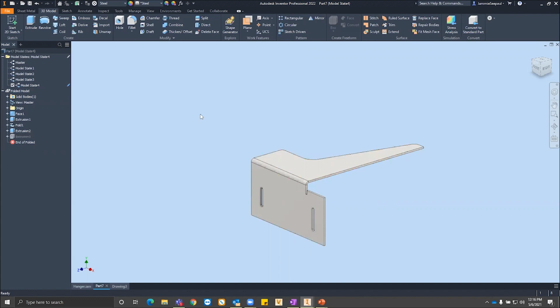Does it still support, because I know when you're modeling inside of a generic Inventor component, you can move around when features occur. So, for instance, if extrusion 2 wasn't reliant on a specific geometry that came before it, you might be able to move extrusion 2 all the way up to before face 1. Is that something that model states will still handle? Yes, you can definitely do that. That's a great question. I appreciate it.